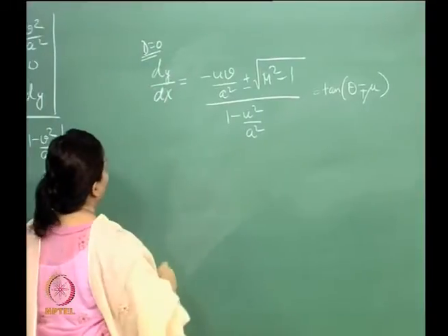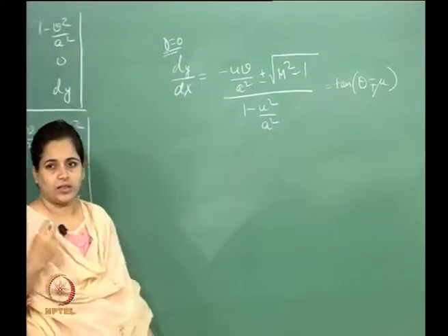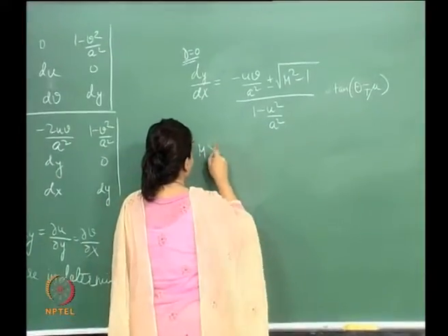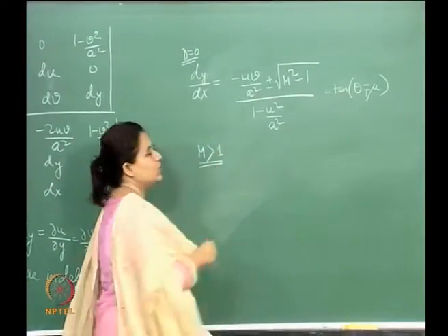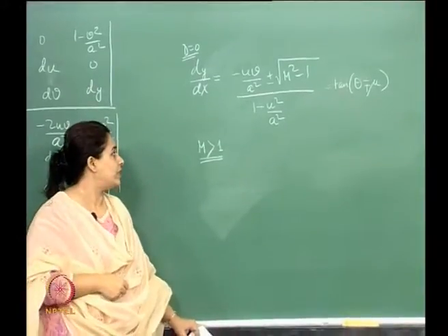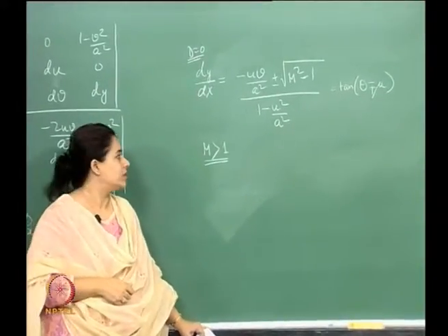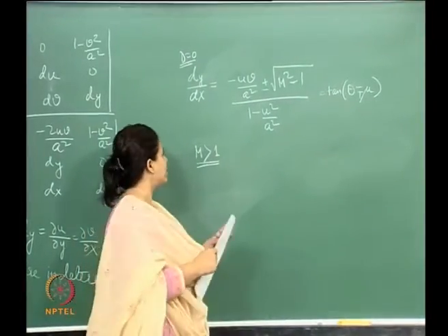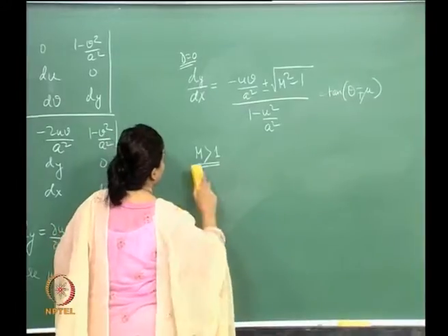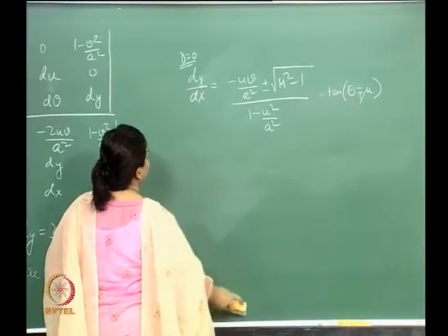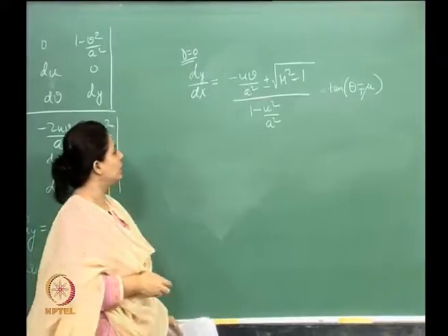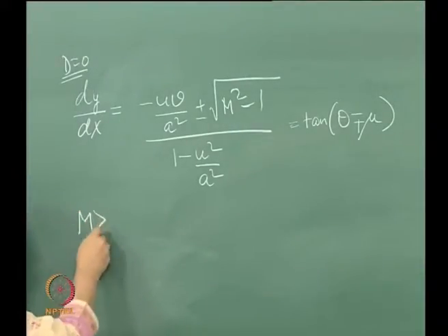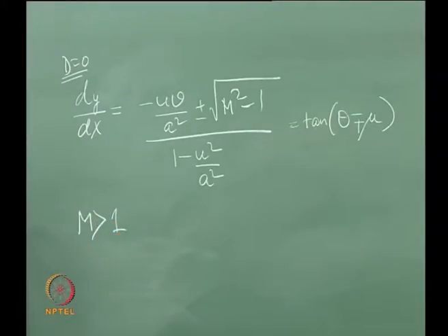So, what this is essentially telling us is that we get two characteristic lines provided M is greater than 1, which is for the supersonic case, and what we get here are hyperbolic PDEs, for compressible flow. For our study here, what we are going to do is consider the case where M is greater than 1, so we have basically two characteristics.